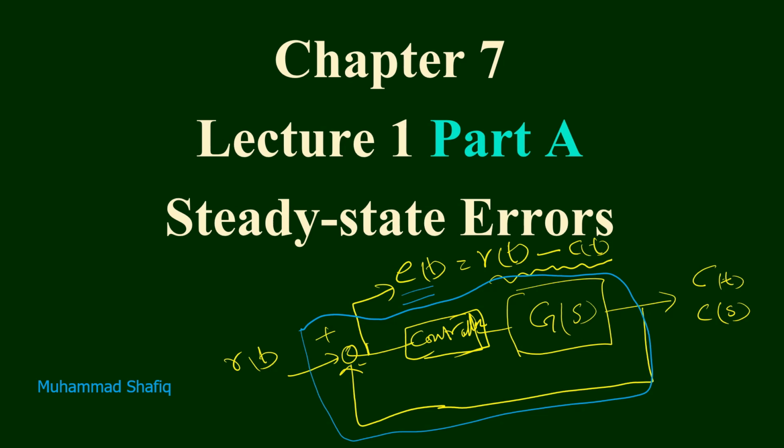Whenever the system is stable, the transient of the system dies out with time, and as time approaches infinity, the transient response also approaches 0. So in that case, what will be the behavior of ESS? This is what we call steady state error, which is normally the limit as t tends to infinity of E of t.